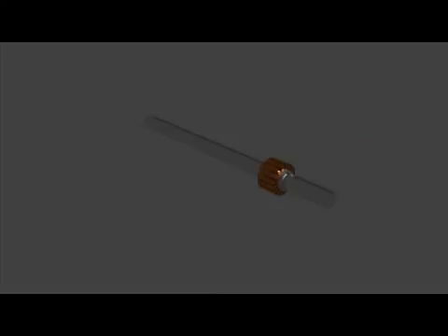It is essentially of cylindrical structure and is built up of high conductivity hard-drawn copper or drop-forged copper. These segments are insulated from each other by thin layer of mica. The segments are held together by means of two V-shaped rings that fit into the V-grooves cut into the segments.